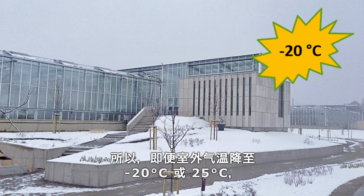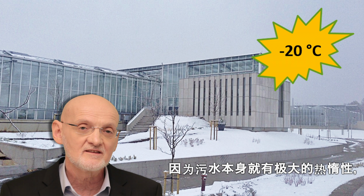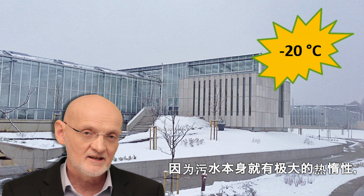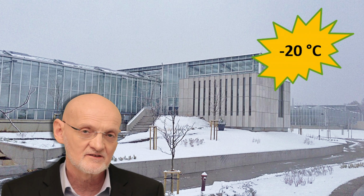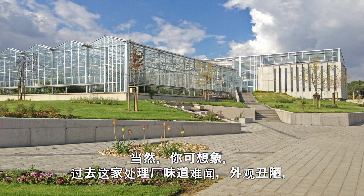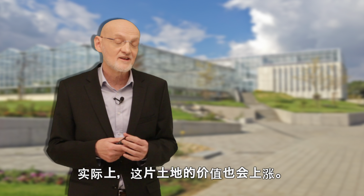So even when the temperature outside drops below minus 20 or 25 degrees centigrade, inside it's easy to maintain 6 to 8 degrees because there is a tremendous thermal inertia of the wastewater itself. So very little additional supplemental heat is needed to maintain the desired temperature. And of course, you can imagine that once you refurbish or retrofit an old treatment plant that used to be smelly and used to be ugly, now, with this kind of appearance, you can start to develop the neighboring real estate, and actually the value of that land will increase.